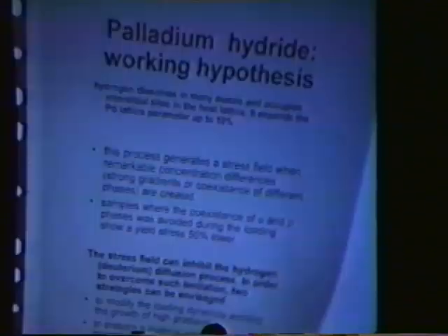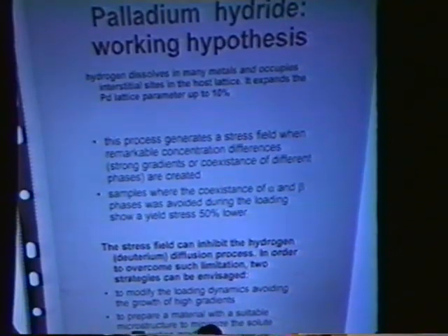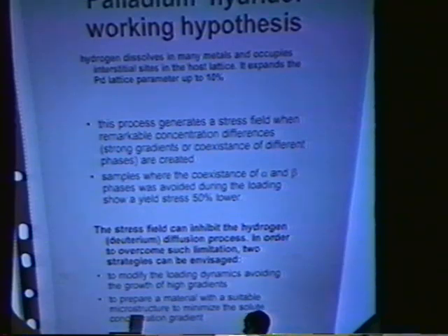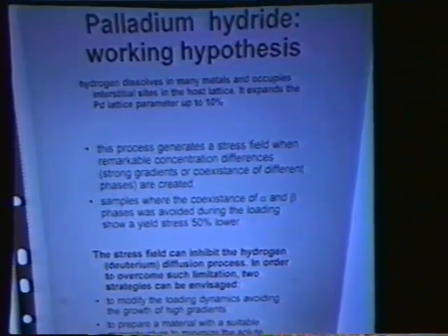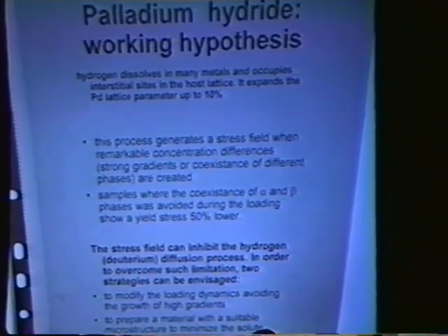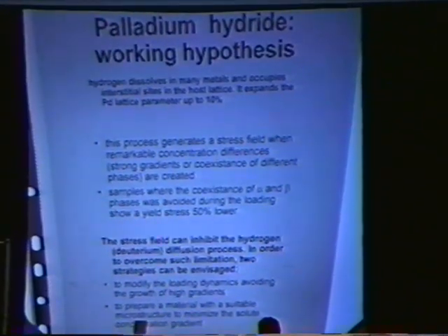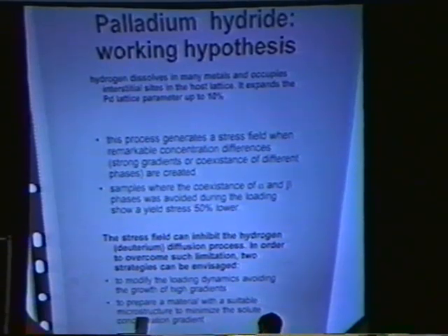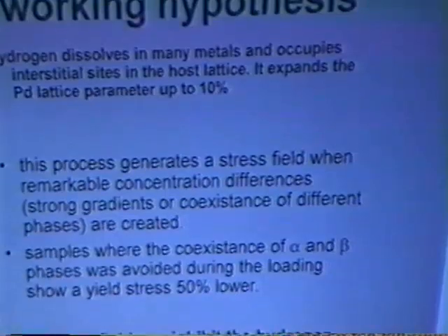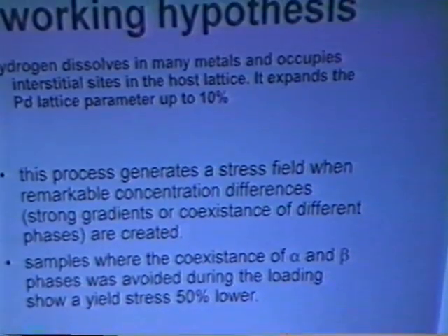First of all, our working hypothesis. We started to study the hydrogen metal system. As you know, hydrogen dissolves in metals and expands the lattice. It occupies the interstitial sites and expands the lattice, and in palladium, this expansion is up to 10% of the lattice parameter.